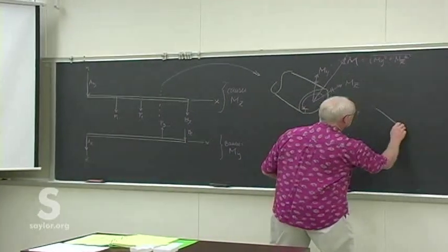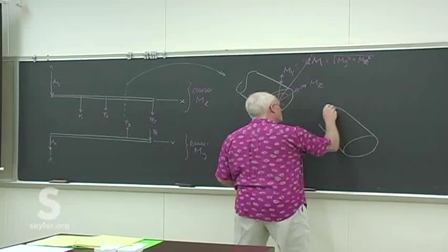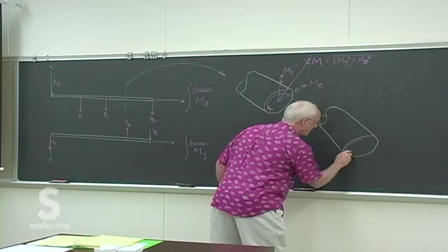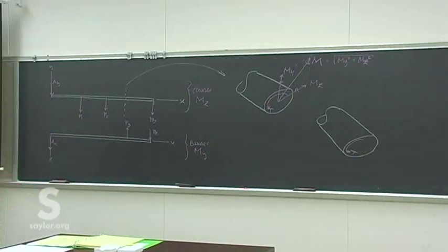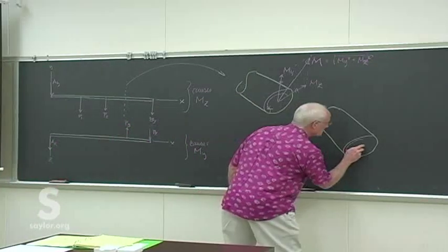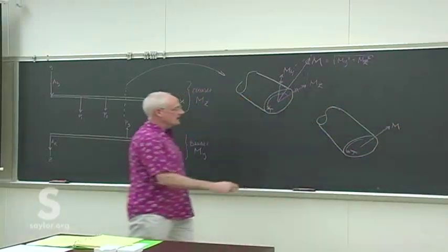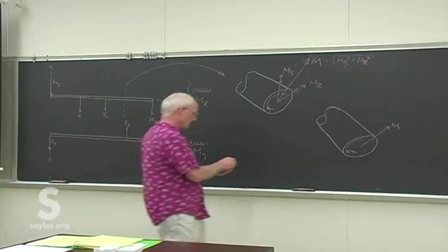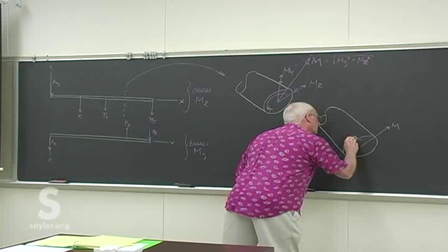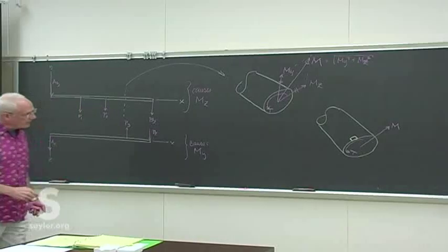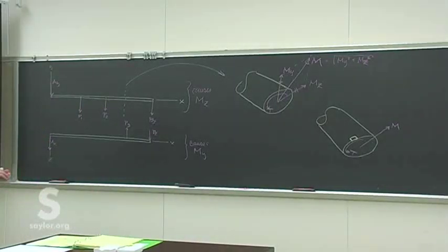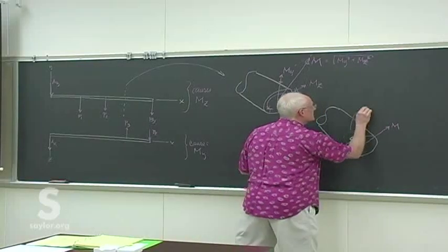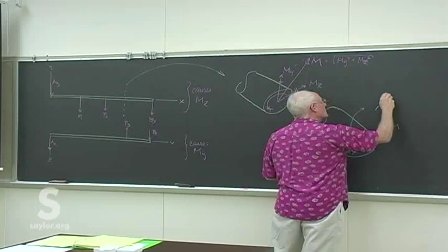So that allows us then to look at this problem in ways we already have. If we've got now some net torsion in this shaft due to those gears, the point where power is taken off and power is applied, and we've got some net moment here made up of the two components in the y and the z direction, then we can do what we've done before, look at a little elemental piece right here at the outer part, because we know that that's where things are going to be the worst. That's the greatest distance. And we can take that little piece and blow it up here for easy viewing.